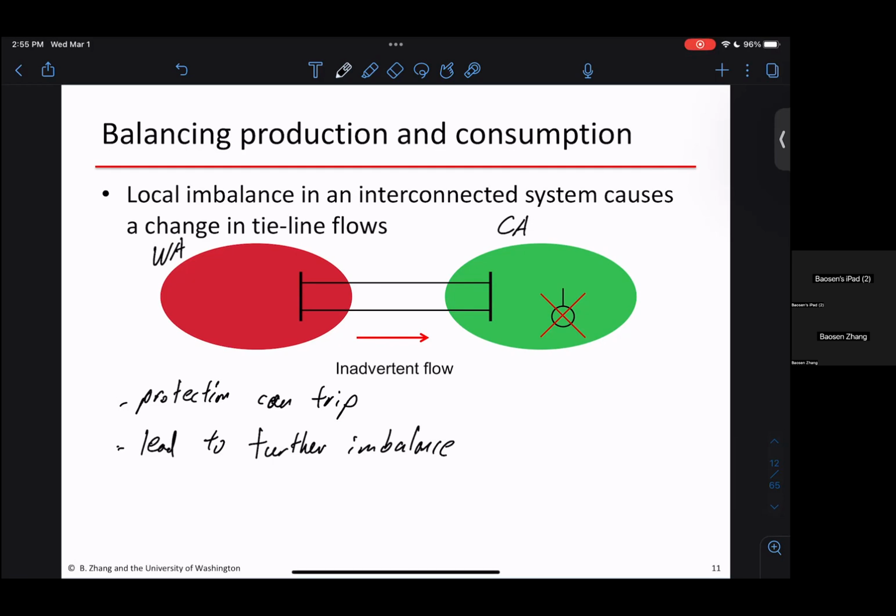So you can trip, right? You can have an outage, then this leads to line overflow. Actually, both lines can trip now. Then you have even less generation coming here, and the frequency gets even worse. So there's a very hierarchical view in the power system. Basically each system should balance its own frequency. Each big enough system, your job is to internally balance your frequency. You typically cannot count on always getting power from somebody else to do your frequency balancing. This is because of this protection issue, this possibility of cascade, so you have to think of each system on its own.